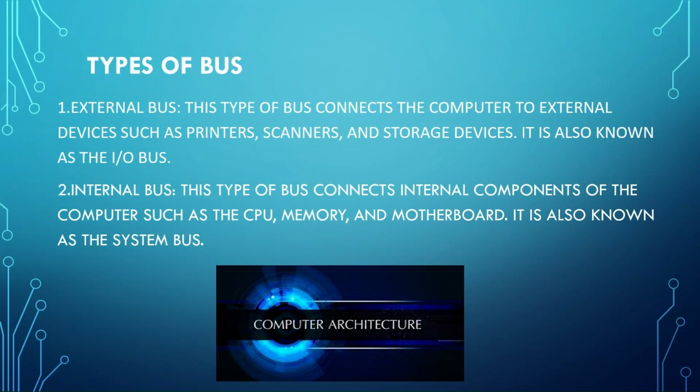Hi everyone, Alok here, and I am going to talk about types of buses. So basically, there are two types of buses, external bus and the internal bus. The external data bus connects the processor to adapters, the keyboard, the mouse, the hard drive and other devices. An external data bus is also known as external data path. You can see the external data lines by looking between the expansion slots on the motherboard. Universal Serial Bus, USB, PCI bus and IEEE 1394 are common examples of external buses.